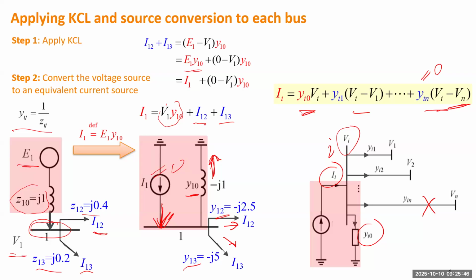Okay, so even if some branch may exist at the beginning, when we consider some contingency, you can open the line. If you open the line, that Y will become 0. Which means under normal condition, you may have all Ys, but if some contingency happens, that can make any Y to be 0. So this standard model is applied to both normal condition and abnormal condition.